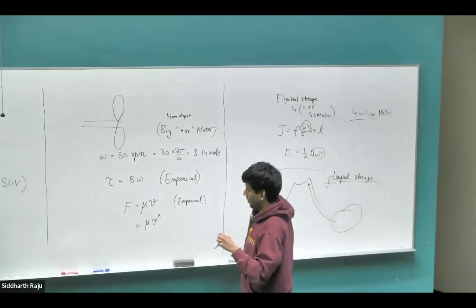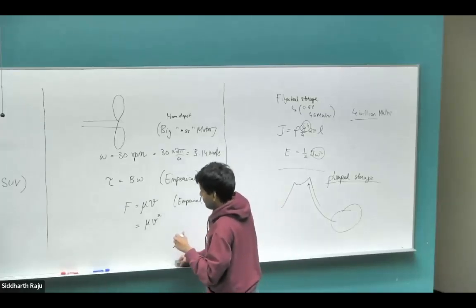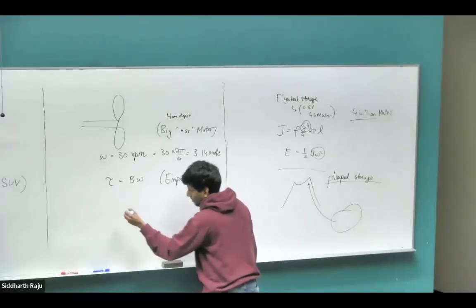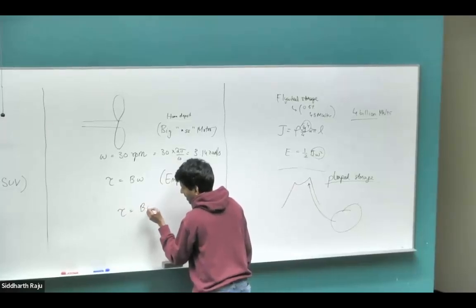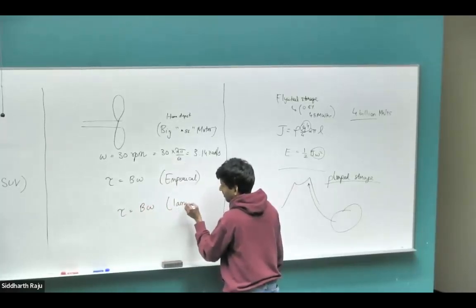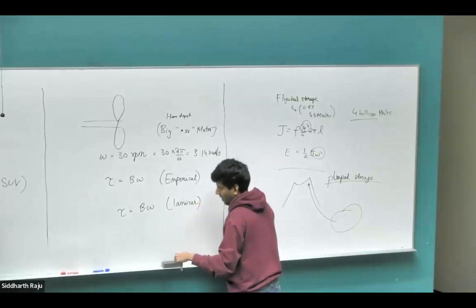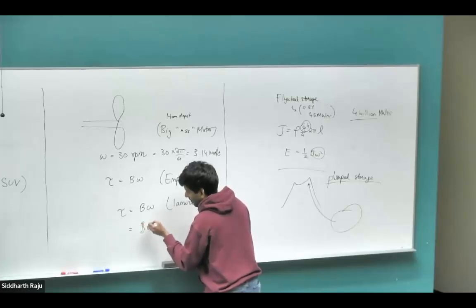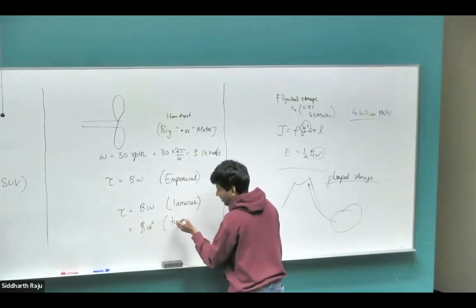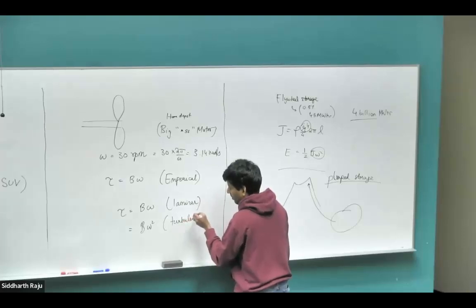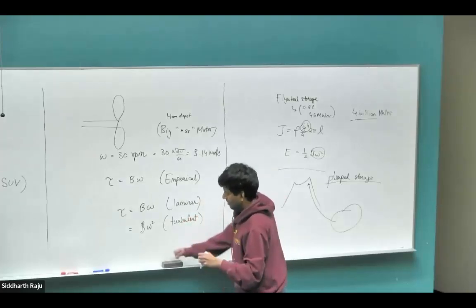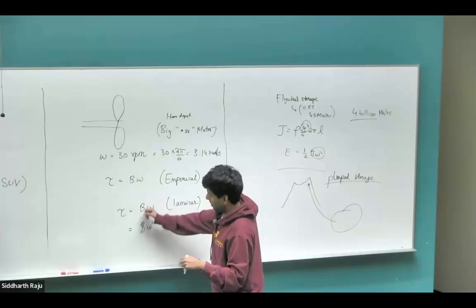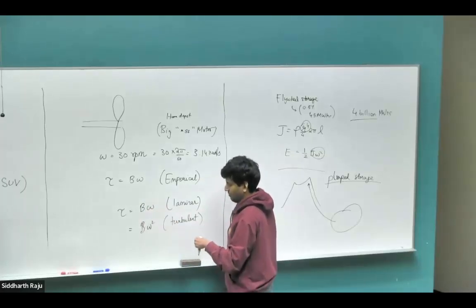Turbulence, perfect. So when you have turbulent flow, let's go back to our rotational system. When the flow is laminar, B omega more or less faithfully represents what's happening in reality. But when the flow gets turbulent, in air or water, B omega square is more faithful in its representation of what's happening in reality. These coefficients B in both cases will not be the same. They will be quite different, right?